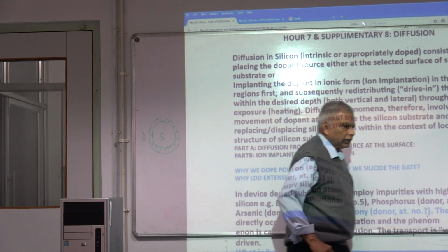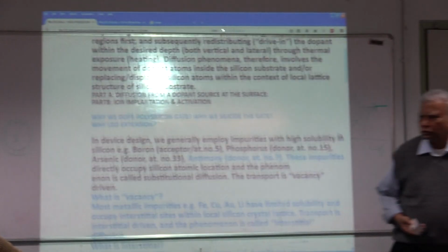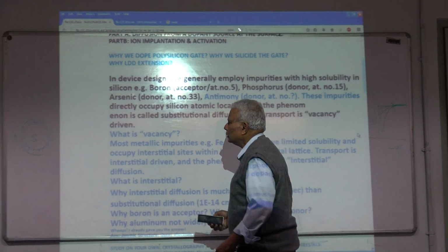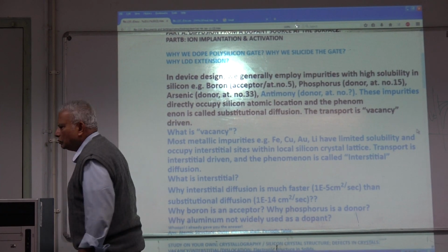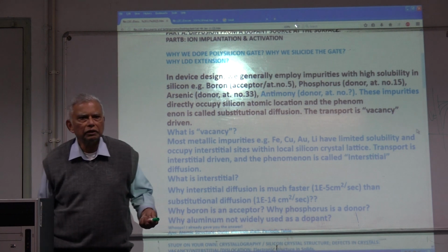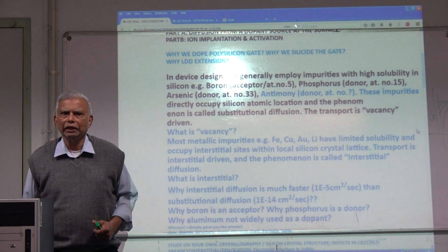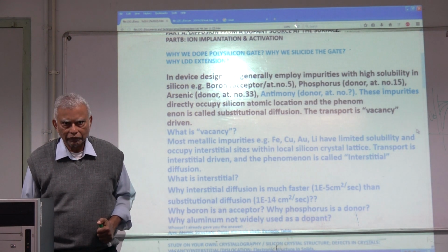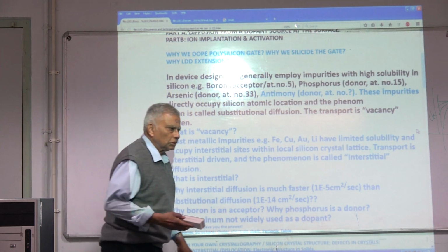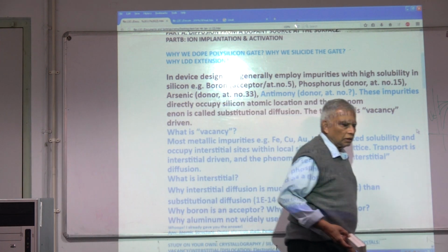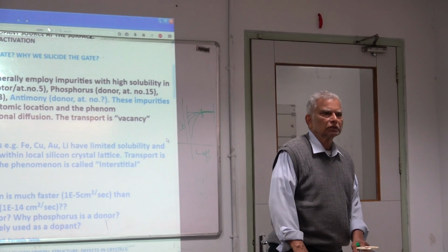When we look at scaling, the first thing we look at is the device point: how can we contain short channel effects? And you know FinFET, right? Some of you are familiar with FinFET. It only goes a certain way and not far enough. That's why the ideal device is this, the future device for 5 nanometer technology.